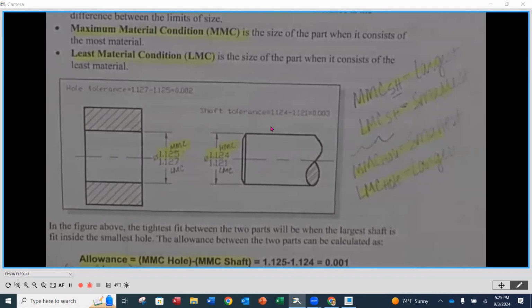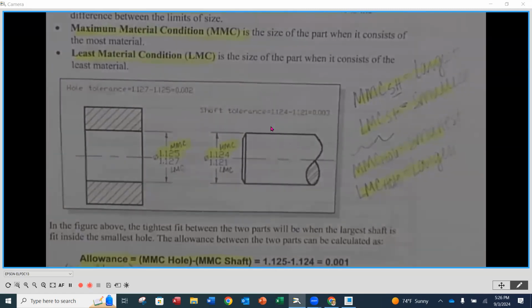You're on the right track, but not quite. What was that? It's going to heat up. Yep, it can heat up. And then what happens to the chips and what happens to the size of the hole as a drill gets dull? Did you have it, James? It does increase, right? Kind of against our intuition.